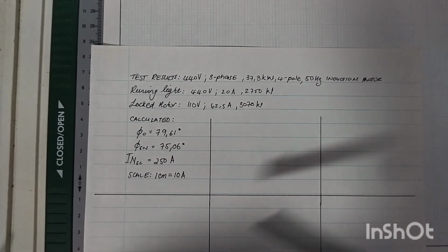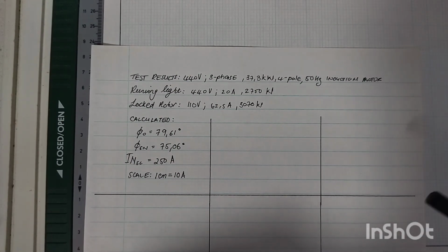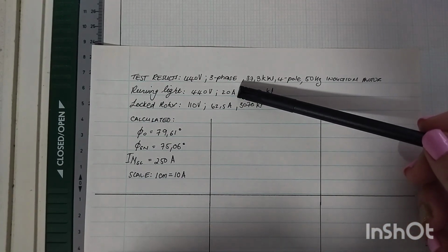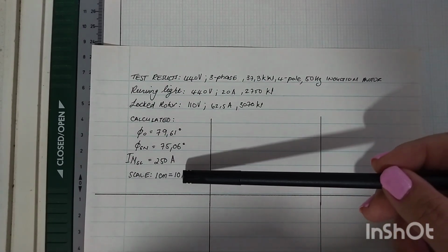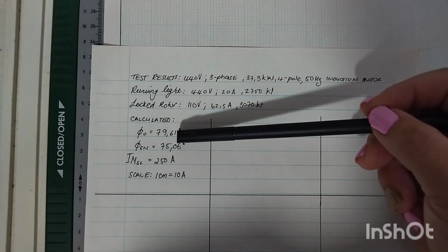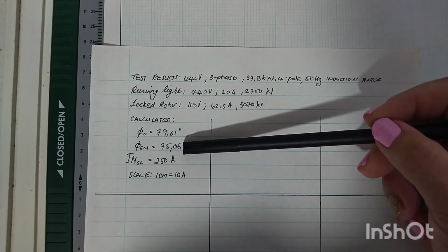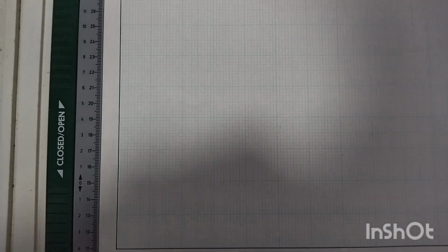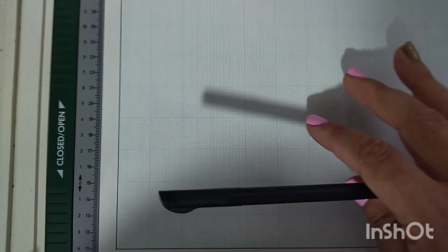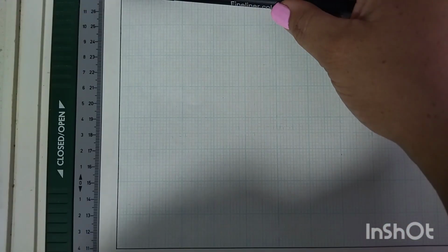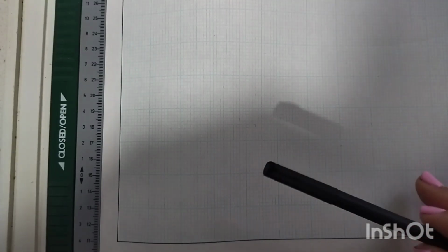Okay, so now I just rewrote all the information down so that I can fit it all into the screen. But now you've got your no load phase angle, and you've got your no load current over here. I'm using a scale. 1 centimeter is equal to 10 amps, and therefore that is going to be 2 centimeters at that angle. Your short circuit phase angle goes with your adjusted short circuit current. So over here I just used the outer perimeter of my graph paper to construct my vertical axis and my horizontal axis, and I said I'm going to try and keep this as simple for you as possible.